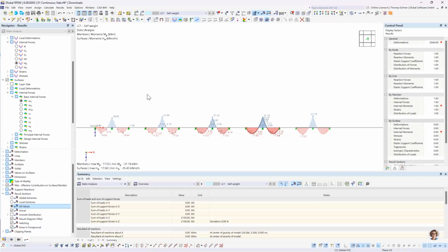But if you think about a 20-story building and you would go for a mesh which is fine like this, or if you think about the dynamics field where we not only have the spatial dimension but also the time dimension, and we calculate these equations once each 0.01 seconds, we will increase our calculation time by quite a lot.